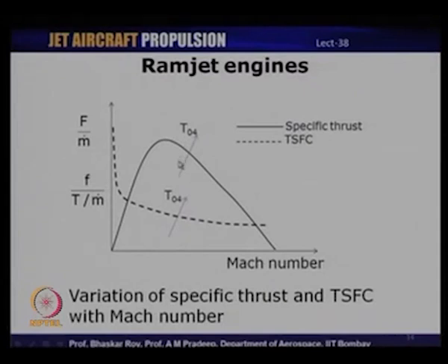Now, if you were to carry out a cycle analysis for a real cycle as well as an ideal cycle, you will observe that both give very similar results, in the sense that the trend would be exactly the same, just that the graph would be displaced slightly. For a real cycle, the thrust would be slightly lower than for an ideal cycle, and fuel consumption is likely to be slightly higher. That is because in a real cycle one would have all the performance parameters put in, like the pressure losses and efficiency and so on. So, for a real cycle one would get slightly lower thrust than what is predicted by an ideal cycle analysis, and you would also end up spending a little more fuel because of all the losses taking place, but the trends remain identical.